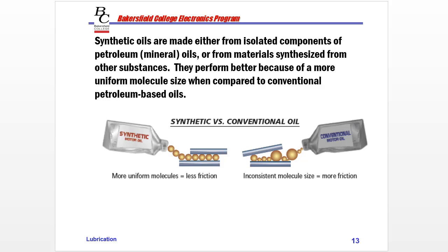If your manufacturer's manual, your owner's manual for your automobile or the equipment that you're maintaining, states using synthetic or a full synthetic oil, then by golly, you should probably do that. Even though the Society of Automotive Engineers for vehicles says that these two will mix just fine and you can use either one. So definitely side with the manufacturer on this, and that's what I would do.